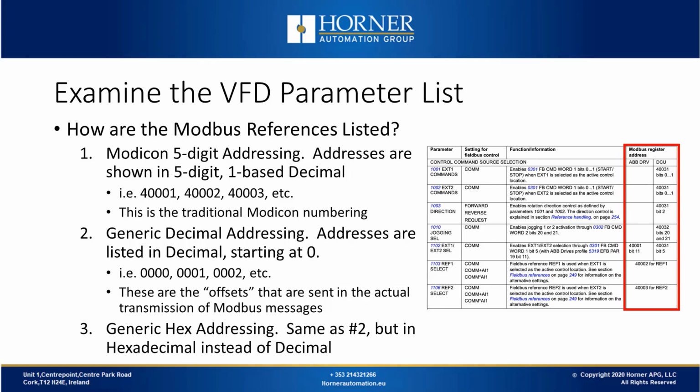Then you're going to continue to look at those parameters from a Modbus perspective. What is the Modbus address that I'm going to use on the OCS side to access these parameters? There's a variety of different ways in which Modbus data is presented in the user's manual. When I show you the OCS configuration, you'll see that we've done our best to try and make what you configure on the OCS side match what the drive has listed in its manual from a Modbus standpoint. We've given you some options on the OCS configuration, but it's important for you to understand what the format looks like.